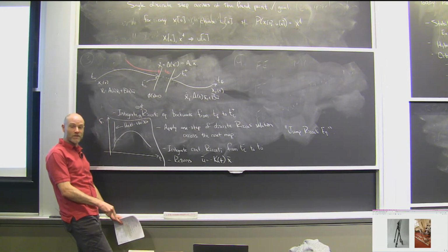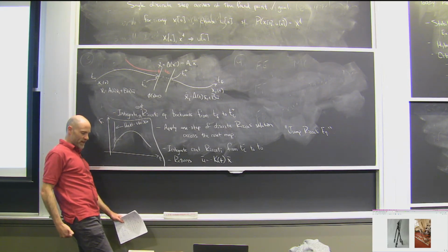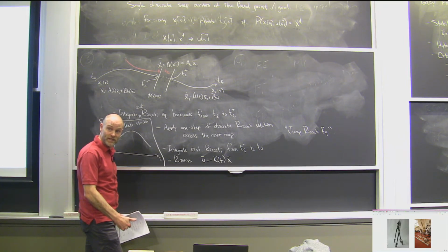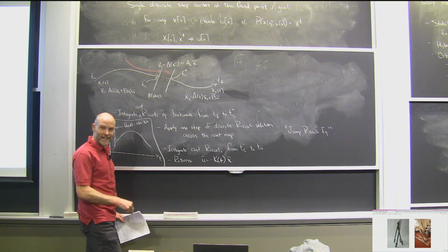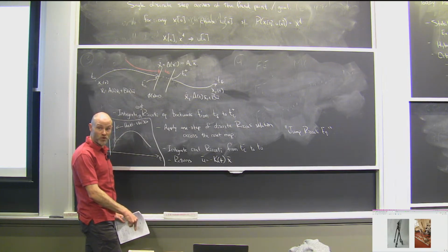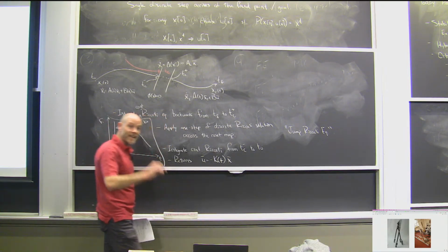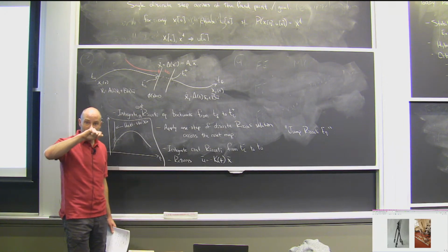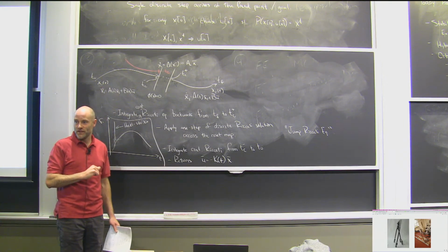If my leg's not on the ground, then I'll potentially be applying a torque to keep my leg up, for instance, so I hit my desired stance angle. The second I'm down, now I'm supposed to be applying force on the ground to pull myself forward, and it can cause, not always, but depending on the nominal trajectory, an absolute sign flip in the torque.